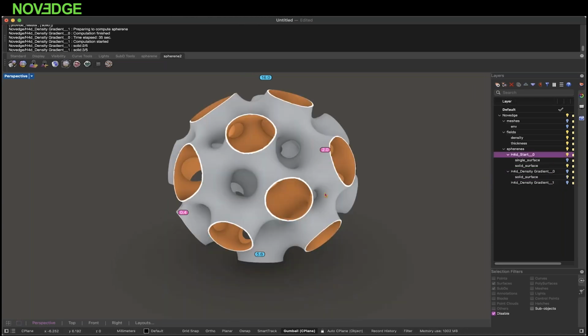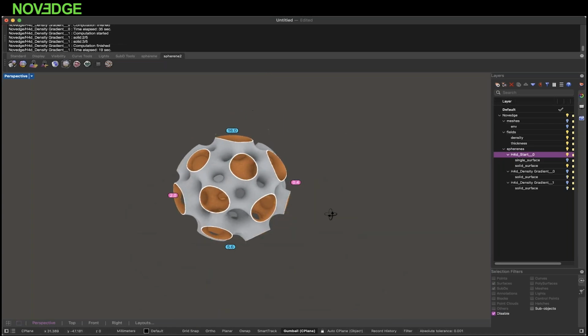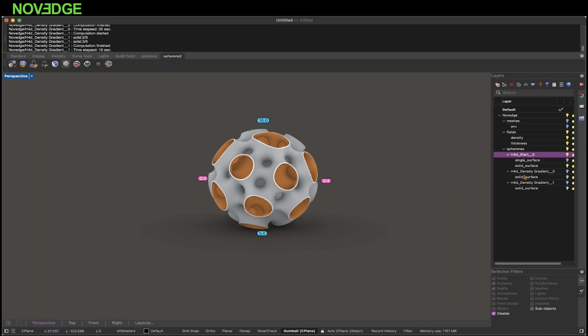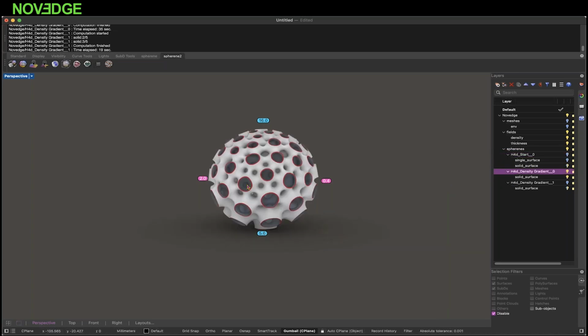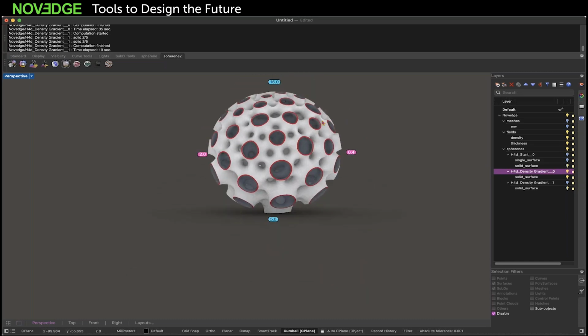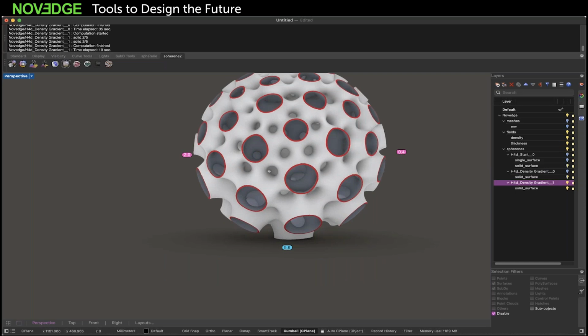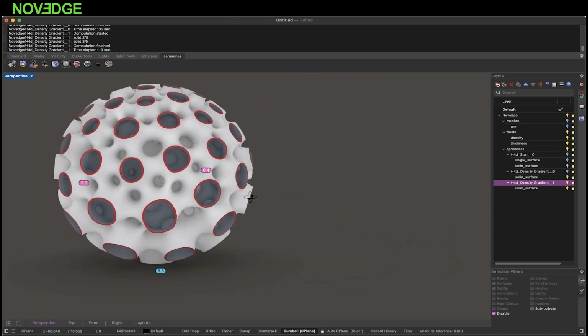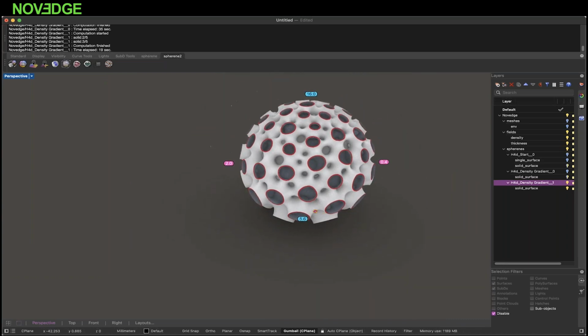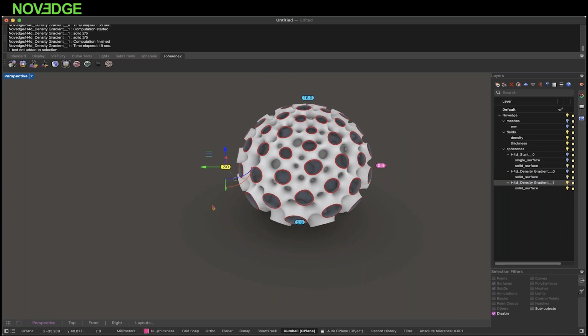So we started with this one here that is a constant density. Then we made the wall thickness change, and first we made the gradient for the density, as we see here. That's the name that we entered for the part. And we have this gradation of 5.6 to 16, as we see. The next one is where we added a wall thickness change from 0.4 to 2 millimeters. And actually, that must be the beta version that leaves me hanging.